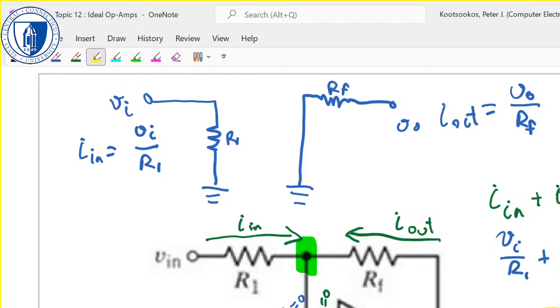And believe it or not, I've just effectively done nodal analysis. There's one node, and I've applied Kirchhoff's current law to this. Some of the other circuits here are more complicated, and there are more nodes, but it's still just application of either Kirchhoff's current law or nodal analysis.